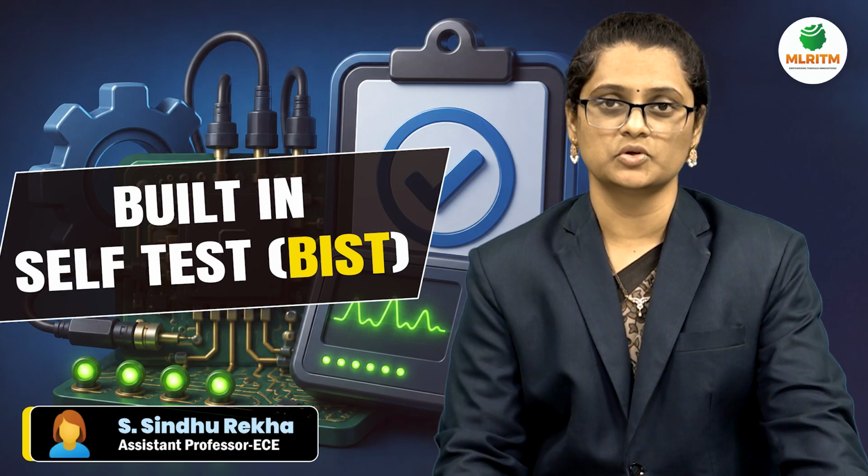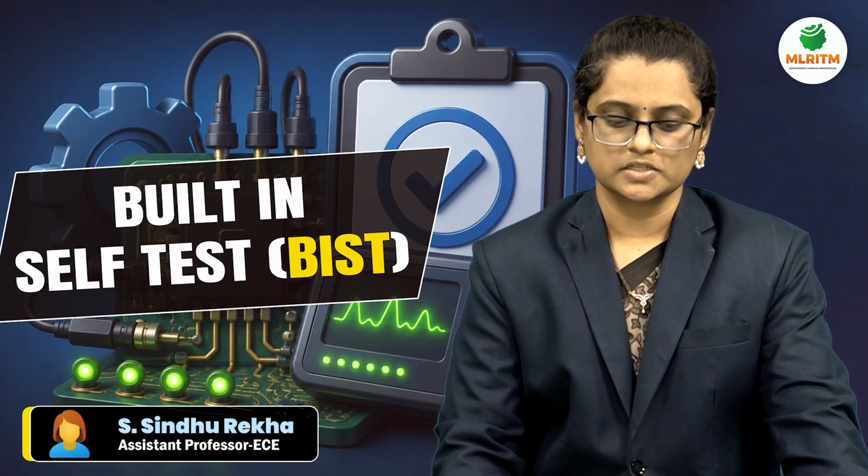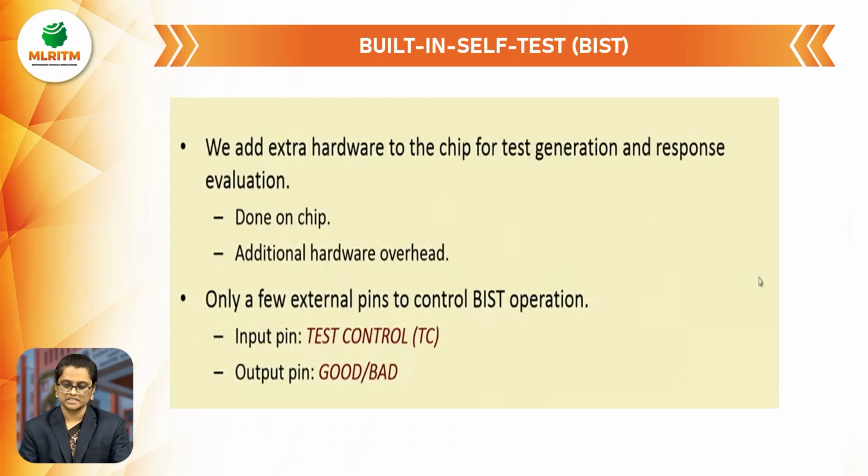Today I am going to discuss the topic built-in self-test, that is nothing but BIST. Coming to the BIST structure, we can add extra hardware to the chip for generating the test patterns and response evaluation. This is done on the chip, and additionally we require hardware and a few external pins to control BIST operation. One is an input pin and another is an output pin. Here the input pin is test control and the output pin is good and bad. Here we can decide whether the chip is in good or bad condition.